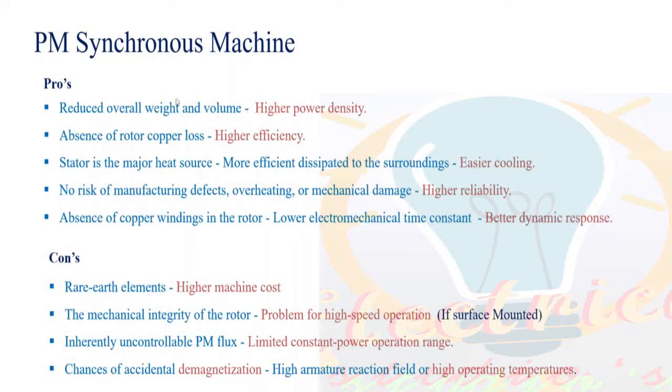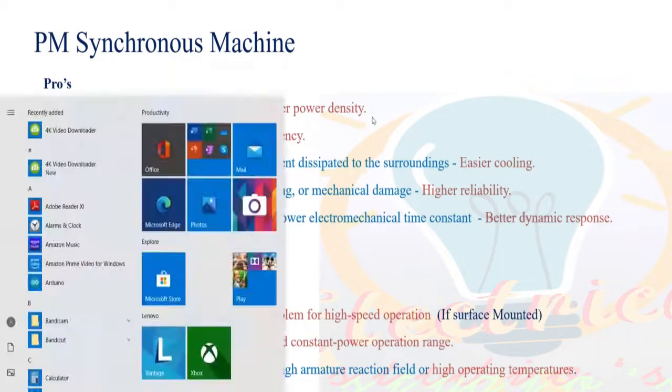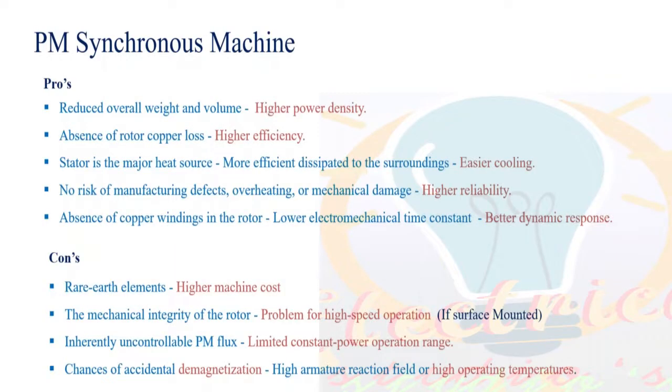So when you look at the overall picture and compare the PMSM motor with other types of motor, PMSM is currently the widely used motor in electric vehicle applications, right? What is the reason? Because the PMSM motor gives a fantastic power density. It gives a fantastic, very high efficiency. Currently, PMSM motors are giving efficiency close to 95 to 97%. That is also one of the reasons it is very attractive for the passenger car market.